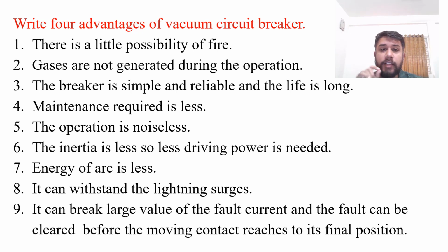So first is, there is a little possibility of fire as the vacuum is the absence of air. So the possibility of fire is very less. Gases are not generated during this operation. The breaker is very simple and reliable and robust in construction. So the life is very long. Maintenance required for this type of breaker is very less. The operation is noiseless, means quiet operation.